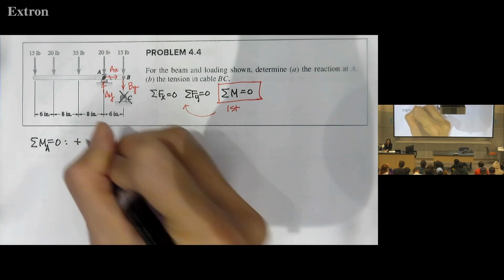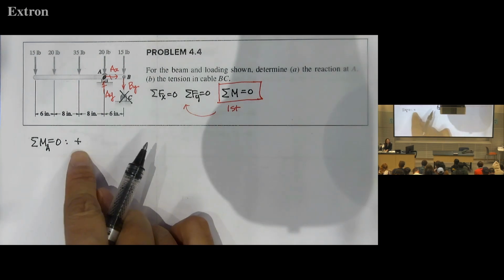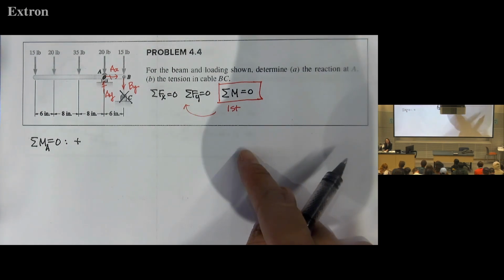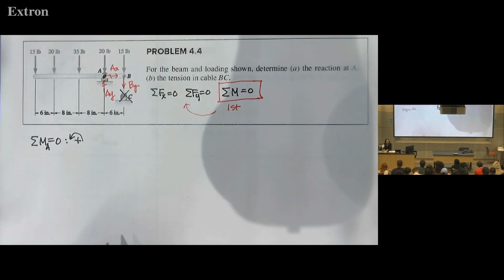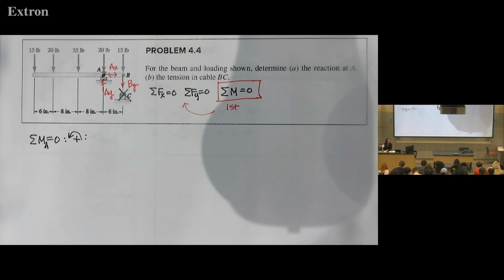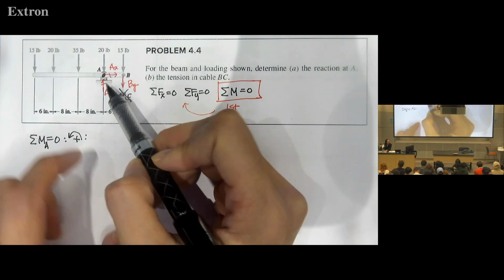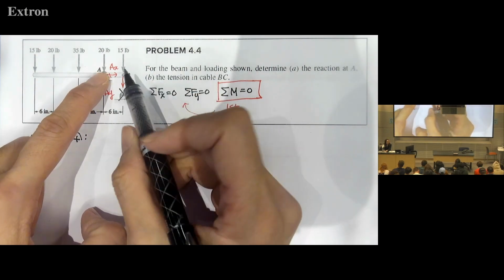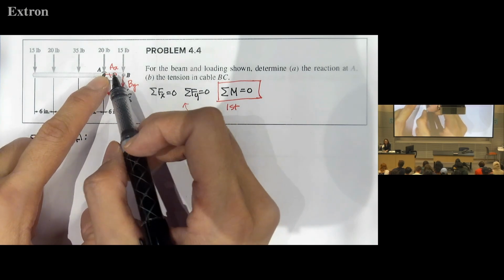Next step is defining the positive direction for moment. This is a sign convention within this equation, so you can choose either clockwise or counterclockwise. So you have freedom to do that. But I typically choose counterclockwise positive for consistency. And then now calculate all the moments based on A. So A is the pivot point, and then calculate moments, so equivalent couple, force couple and the couple, right?